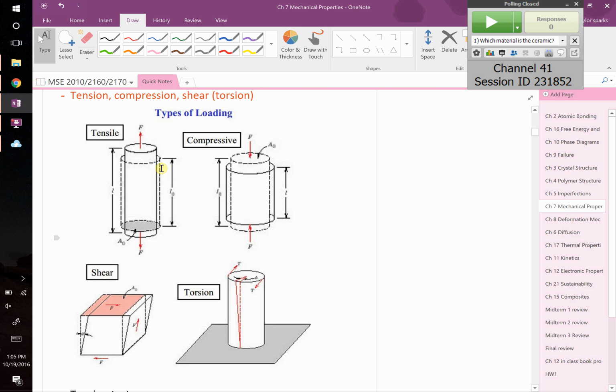After you apply a load, this is pulling it apart by taking the force and loading it perpendicular to the face. We get this final shape with now the solid lines, not the broken lines. So it's stretched out and it got a little bit skinnier, right? If you apply a load in compression, we now call this a negative force, just by convention. We call negative forces compression, right? And its initial shape was here, but its final shape is now shorter and sort of squattier, right?